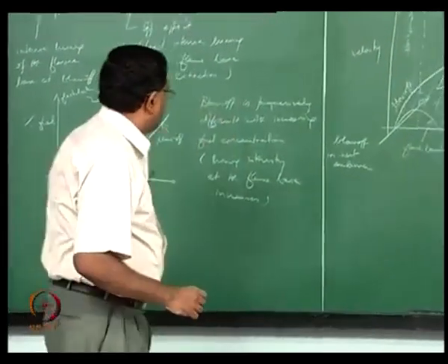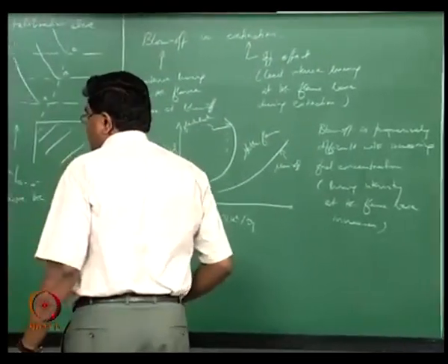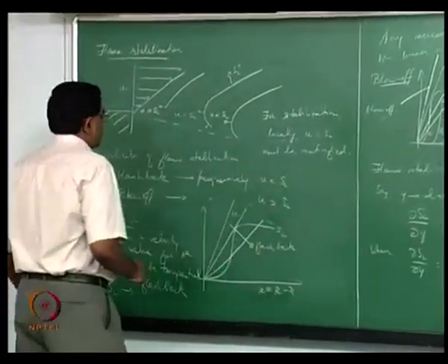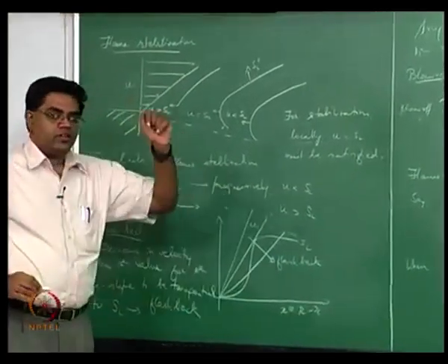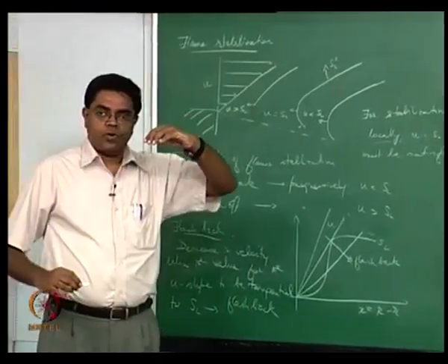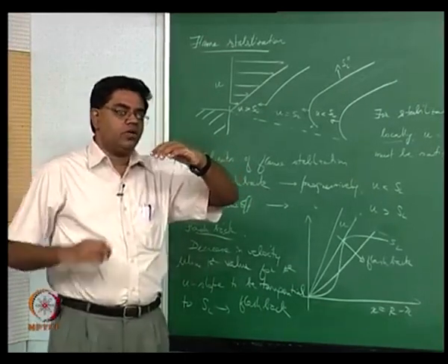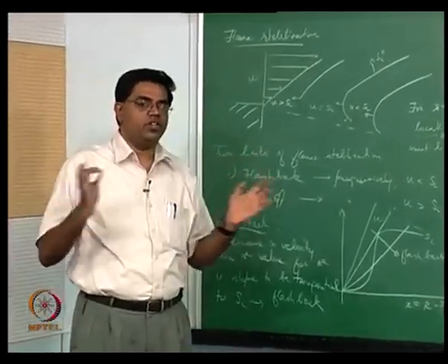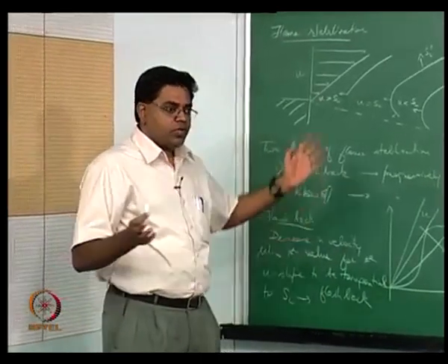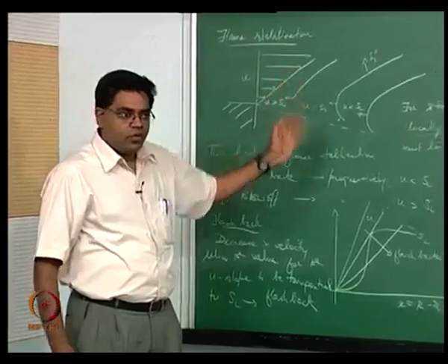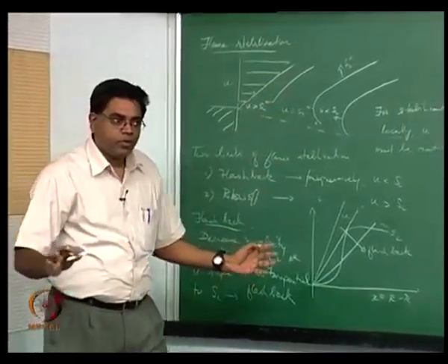I would like to point out one thing that we have not talked in detail at all, or as a matter of fact not considered. When we did the tip, we talked about flame stretch effects, which is to take into account the flame curvature and flow divergence effects. When we talked about the flame base, where the stabilization happens, we haven't really bothered about that at all, okay?